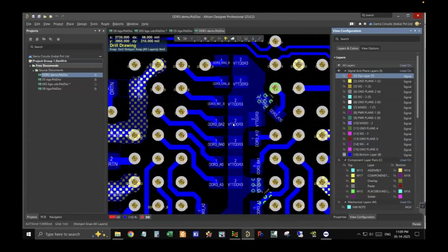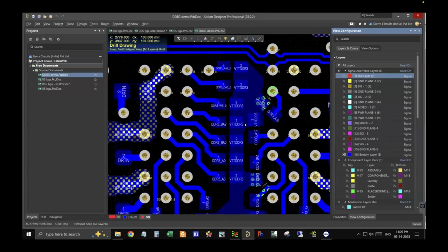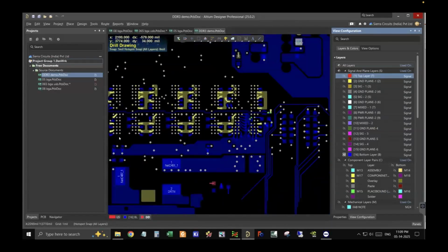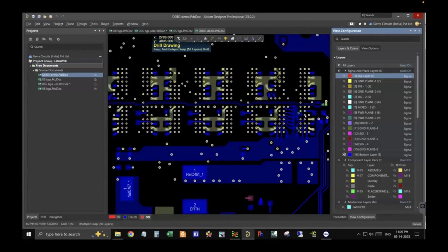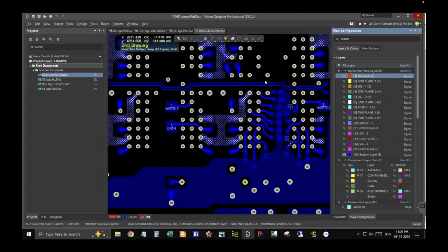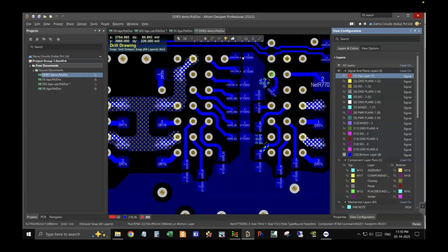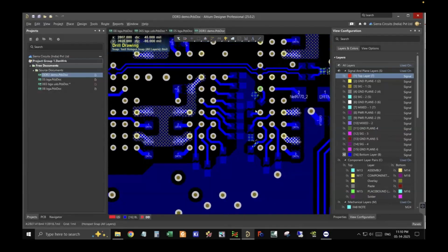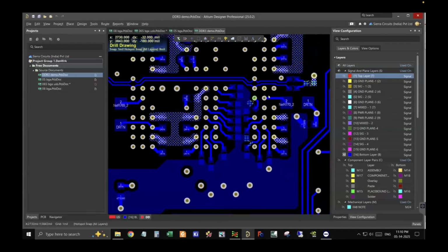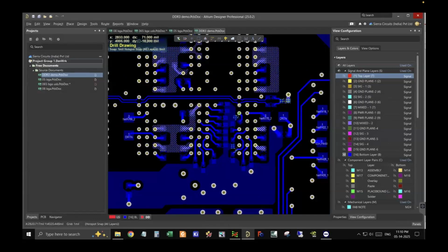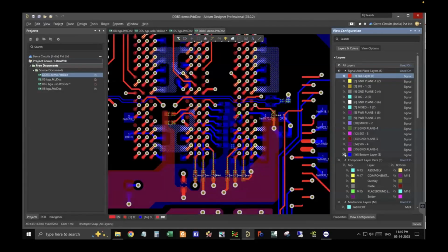These are not 0201 sizes; initially the customer had selected large sizes, 0603. So we had to place them wherever the space was available, because they were not fitting over here. Due to that, some discontinuities were created in the impedances, and it was creating some distortions in the signal integrity when the simulations were done. The solution was to reduce them to 0201, because that is the only way we can put them very close to these wires. So that's what we did, and they were placed at the end of the daisy chain, which is the last line in the sequence. That resolved the problem.